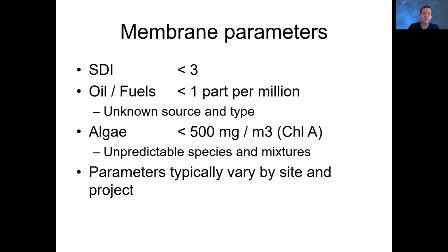These fluorescence instruments being instantaneous, producing a fast response, you'll see the very beginning of an oil spill or algae bloom or whatever has happened there and can prevent damage to the membranes. So our devices and most fluorescence devices can measure low concentrations like this. And so whether we're at 0.1, 1 or 10 ppm, the fast response is really the pertinent factor in protecting membranes.